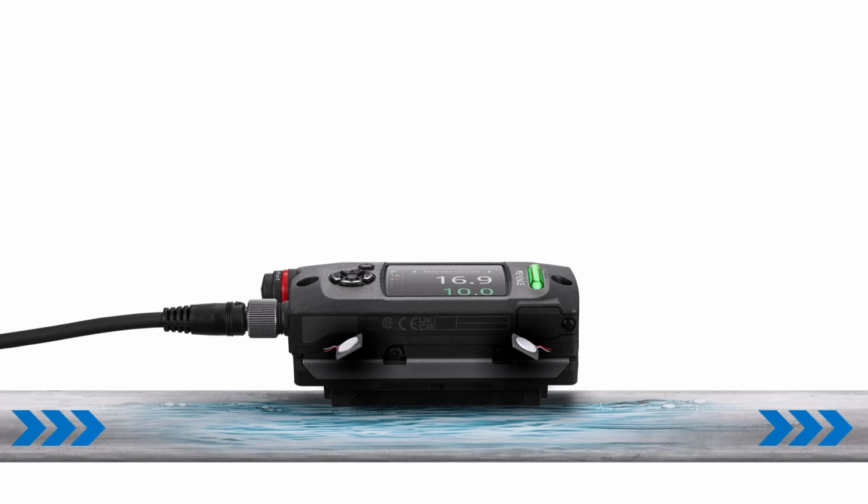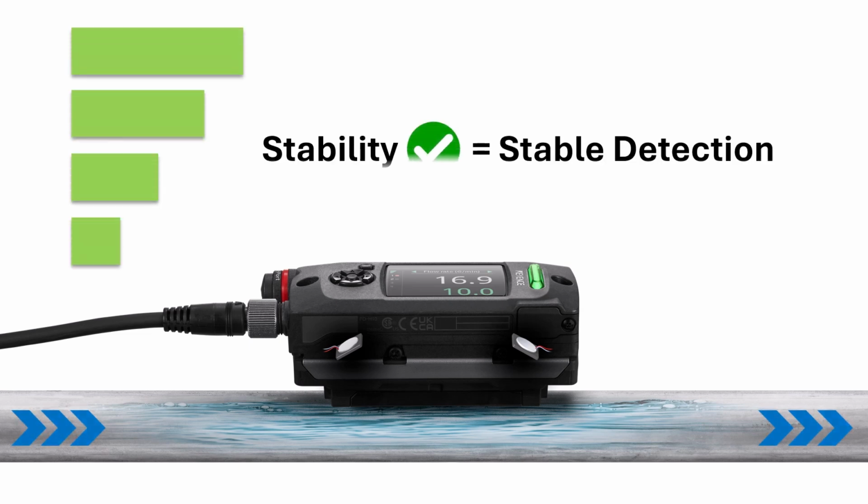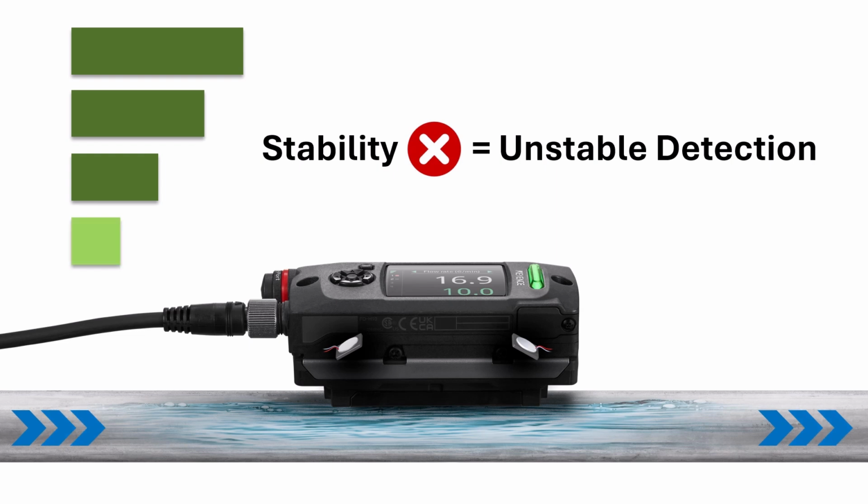Stability bars are analogous to cell service bars on your cell phone. If you have no cell service, it will be very difficult to make a phone call. Similarly, if the flow meter has no stability, it cannot stably detect the flow and may show inaccurate and unrepeatable values.